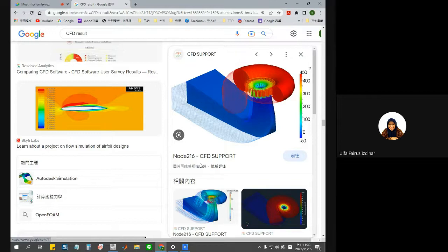For the inlet, you need to specify the volume per unit time to represent the speed of the fluid. And then you need to cut this whole thing into mesh. And usually for fluid, it's very complicated. You need to specify the wall conditions, such as, do you have boundary layers?